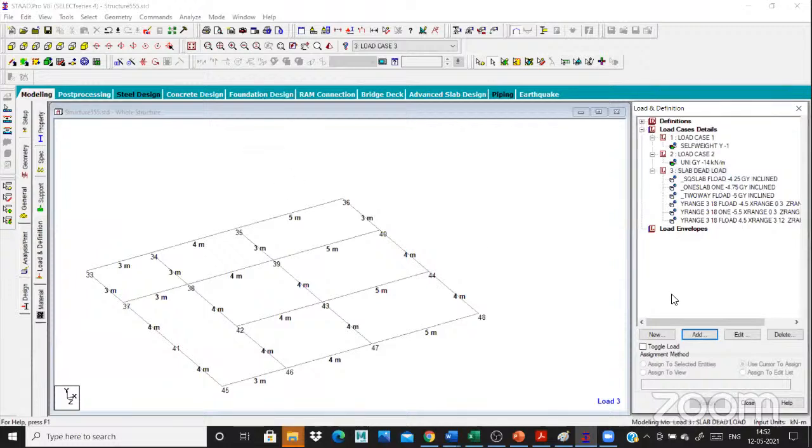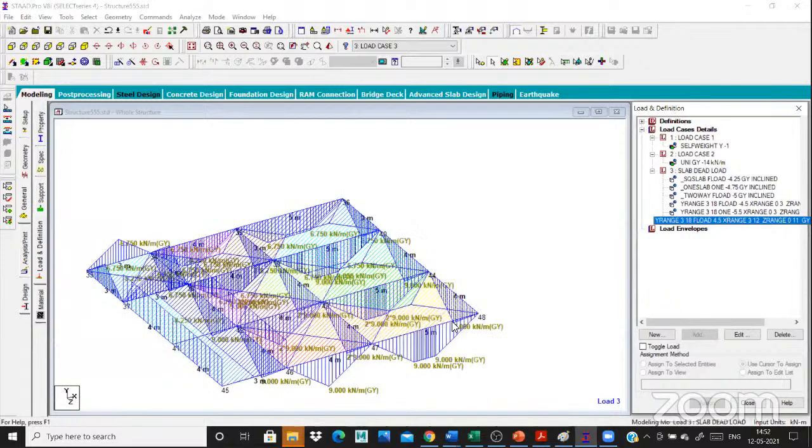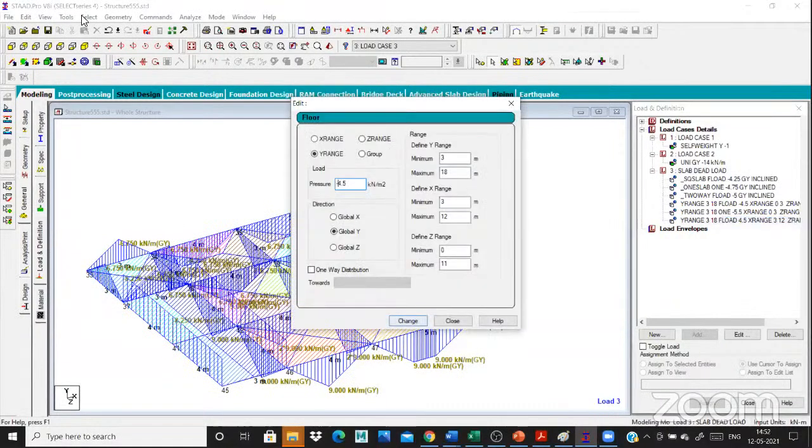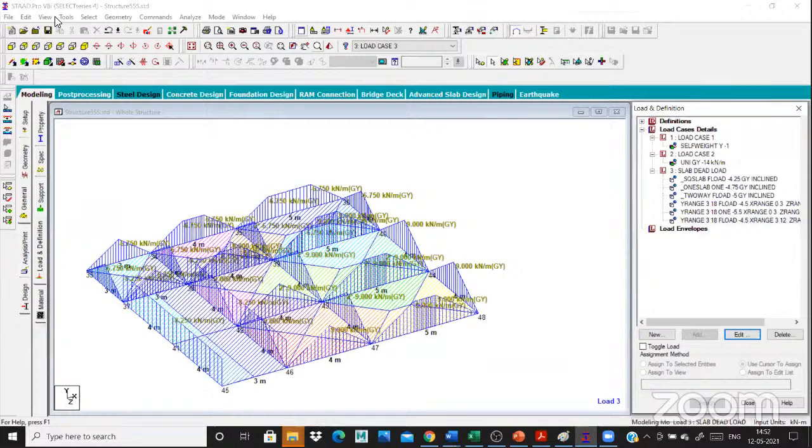Okay. Simply go to the gravity. Simply go to minus, change it. Then go to select, go to tools, set cut section, show all. So all the floor loads will be created: one-way distribution, two-way distribution, and other square lines. This is another method. I will create the dead load, the same procedure as a live load also.